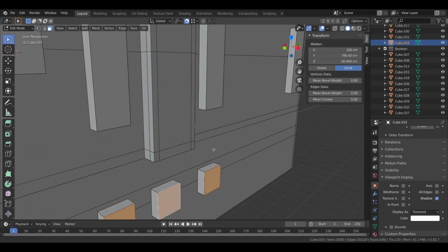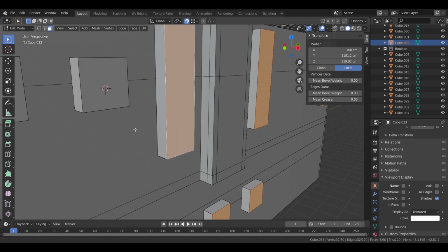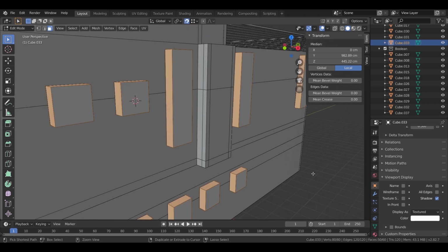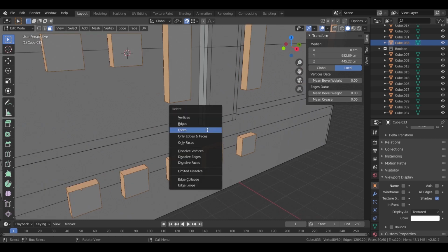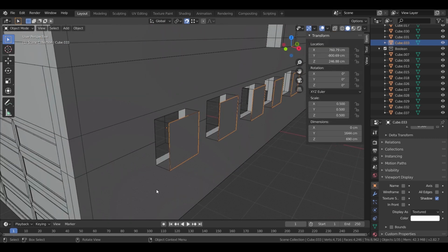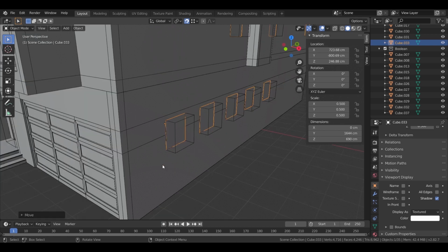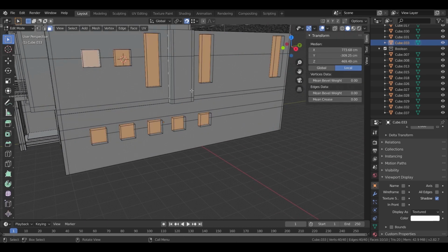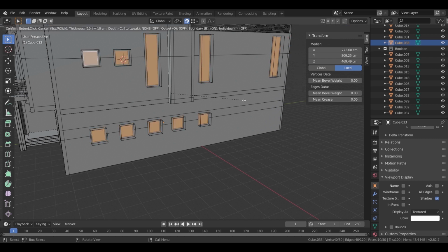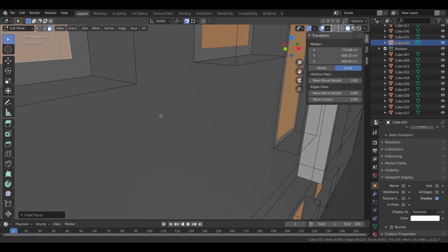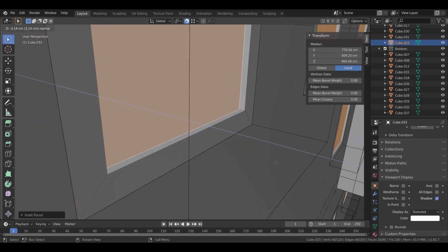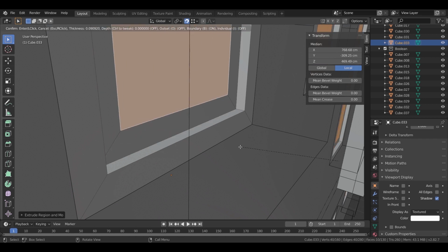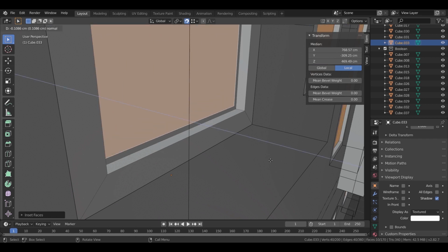In the edit mode, select all faces that we need to keep as you see, then press Ctrl I to select inverse and delete those faces, snap the rest to the walls. Press Ctrl A to apply transformation. Now in the edit mode, same inset extrusion process, inset by 10, extrude by 5. Then inset by 2, another extrude by 2, and finally inset by 2.